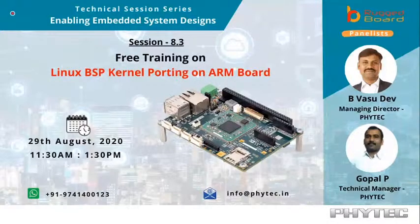We have a couple of off-the-shelf devices, but we can also quickly develop and help with your project in case you need quick prototyping. This is the reason why we have made the design of the rugged board very modular, so that peripherals or the sensor part, the analog front end, can be easily connected. Most of the time analog front ends are connected via the SPI bus, which is already part of the microbus expansion connector.